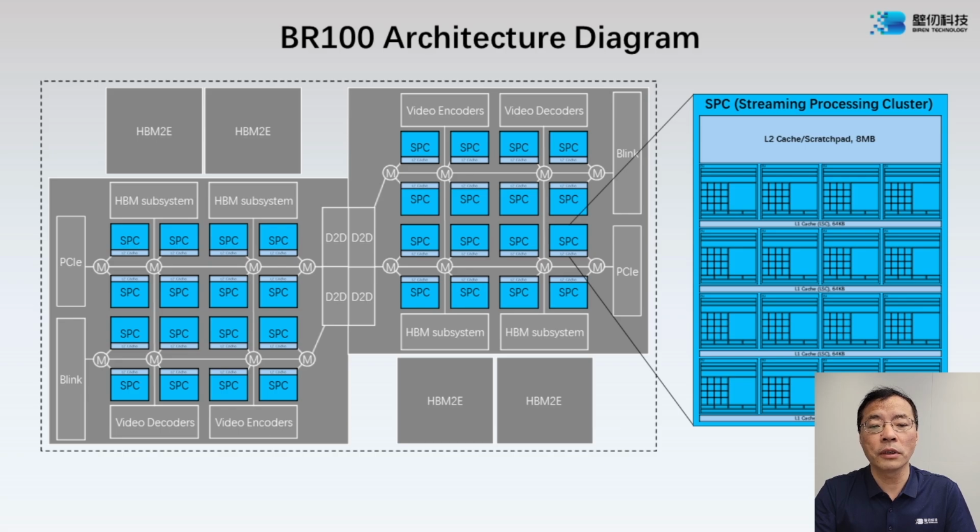Unlike traditional GPUs, usually populated with a relatively small L2 in the middle of the chip or near the memory controller on the side, BR100 has a 256 MB global shared on-die L2 cache associated with each compute cluster and connected by a 2D mesh-like NOC system with multitasking capability. The NOC can multitask weights for data parallel and also activations for model parallel. This distributed cache and data transfer system is capable of providing enough data bandwidth to nearby computing cores for best efficiency. The average data transmitting distance is significantly reduced.